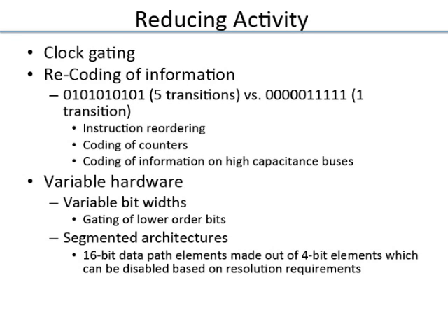Here is another technique, what I call variable hardware. What I mean is, you design your chip, you design your circuit, but the amount of hardware you use for your computation, you change based on what is required. Now, really, is it reducing alpha I or is it reducing alpha I times C? It doesn't matter. Essentially, you are reducing the amount of switching capacitance.